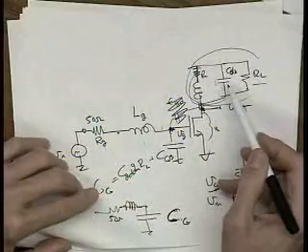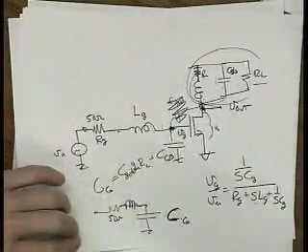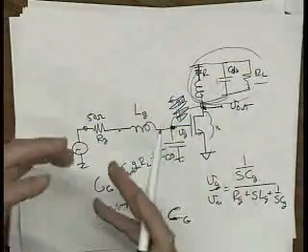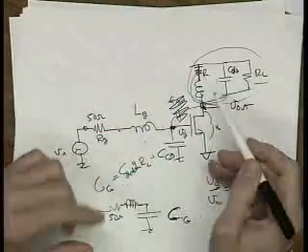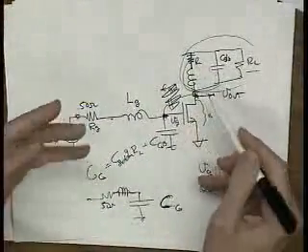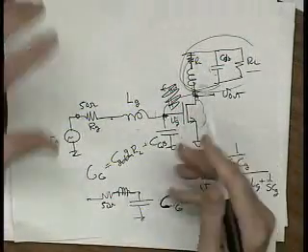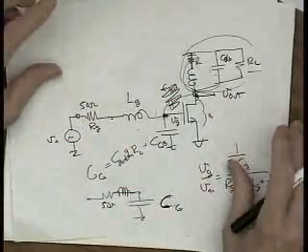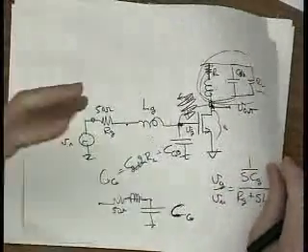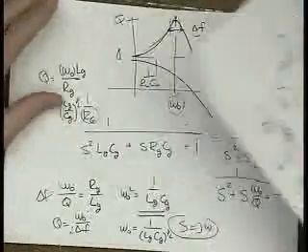So they do take area, so they are costing us something, especially as we go to higher and higher, more scaled technologies. These inductor values are associated with these parasitic capacitors, and so they're not going down as fast as we'd like, and so these inductors become more and more dominant to us. They're taking more and more area, and area is cost, right? So that's not good.